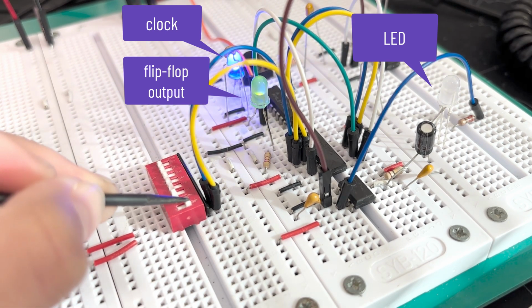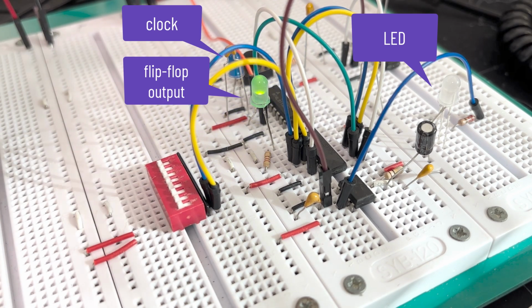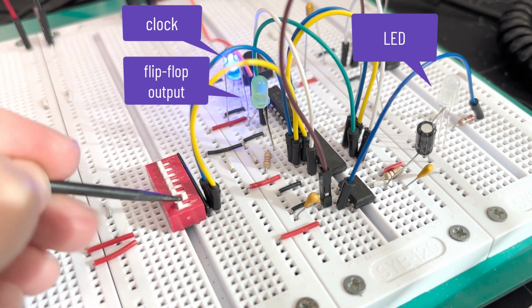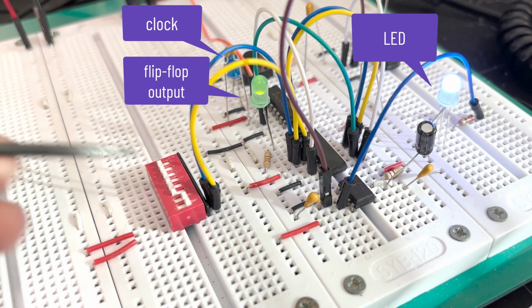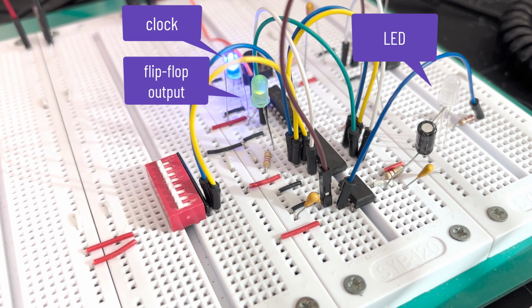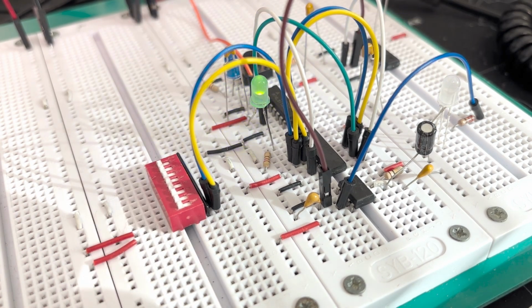This specific example is a great use case for a Mealy machine because the trigger input for a 555 timer in monostable mode should be asynchronous, as any low signal on the trigger pin causes the output to be high. This means that long trigger signals can affect the duration of the LED being on. Because the value of T in this circuit is asynchronous, I don't have to worry about the value of T being asserted low for longer than it takes for the clock to tick, keeping the trigger pulse short enough not to cause the output to act unexpectedly.